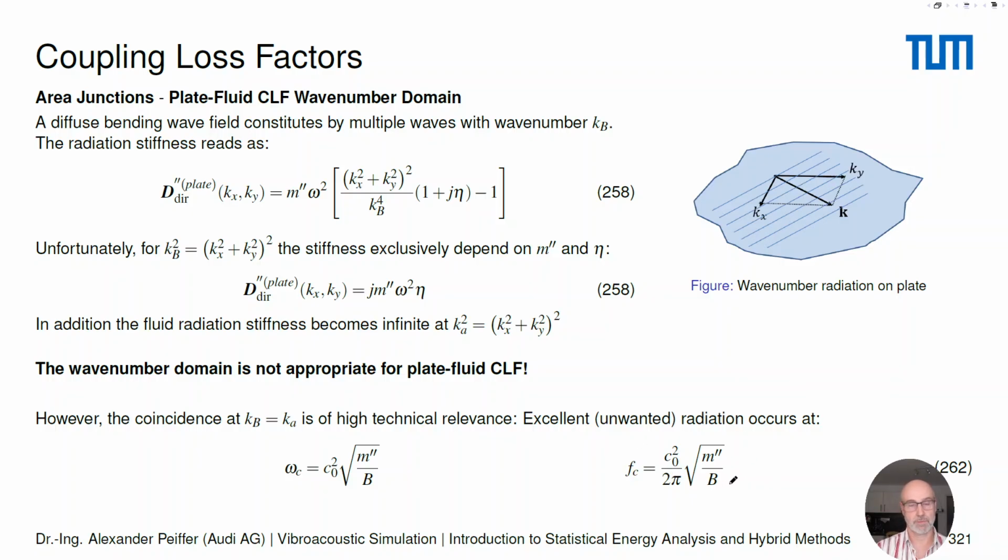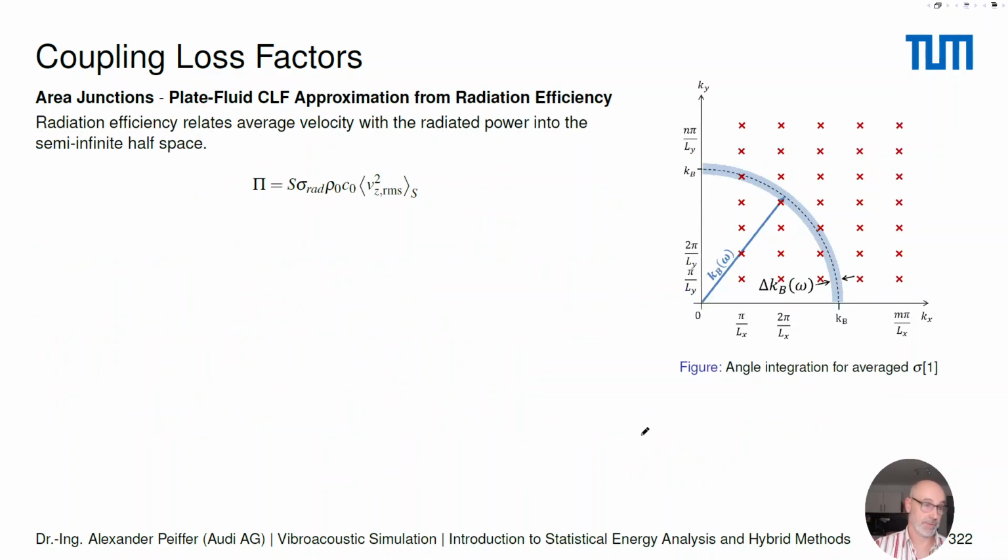That means you have to take stiffness out of your plates. But unfortunately, all the other guys in technical systems, the engineers, need stiff plates, because this is what they are used for. So this is a typical target conflict. Good. However, that means if we need to calculate the coupling loss factor of plates, we are lost, we can't use it, which is a pity.